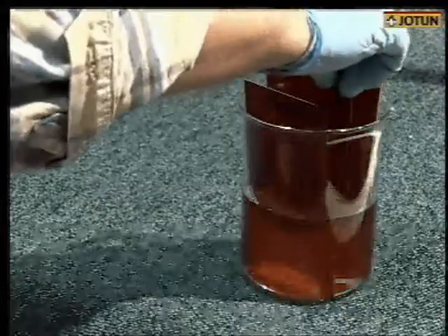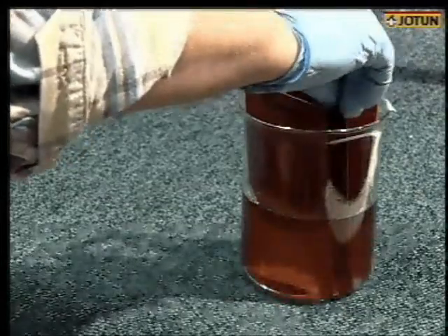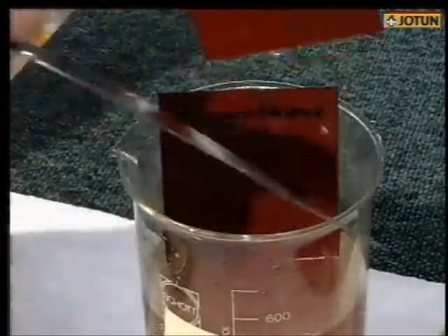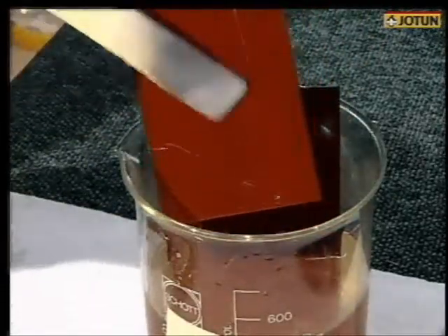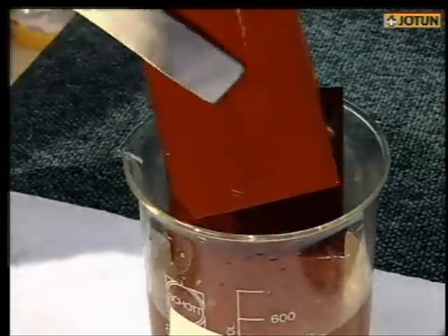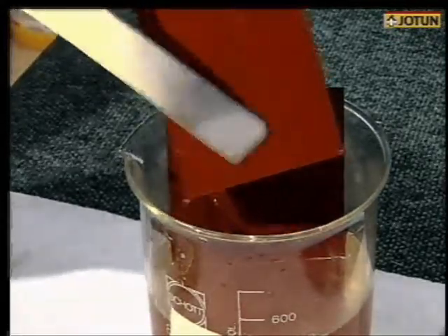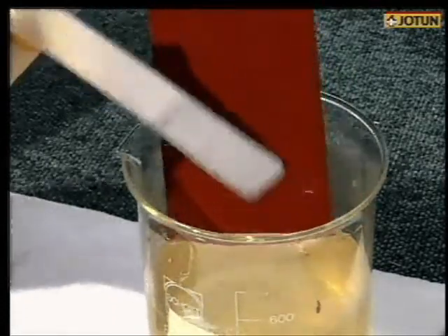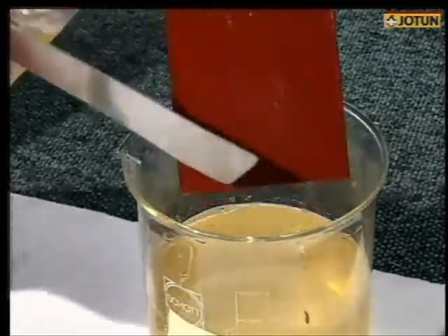As an example of the chemical exposure test, we used caustic soda, a strong alkaline solution. The alkyd swelled and flaked off, while the epoxy and the polyurethane showed good resistance. Please note that most generic types of paint are modified in various ways to give improved properties for certain applications.